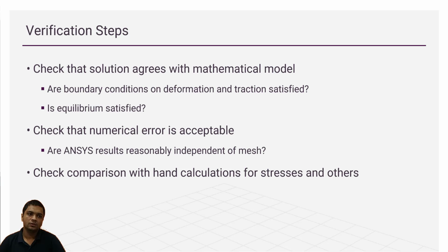Now we're going to do the verification steps. First is check that solution agrees with the mathematical model. Are the boundary conditions on deformation and traction satisfied? Yes, we have checked that at the fixed supports we are getting the deformation of 0 mm. Second, equilibrium satisfaction. So applied force and reactions are matching.